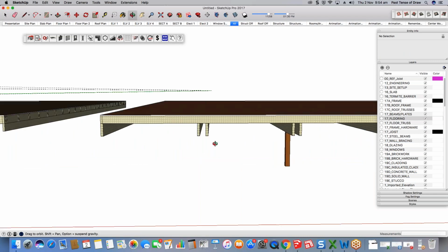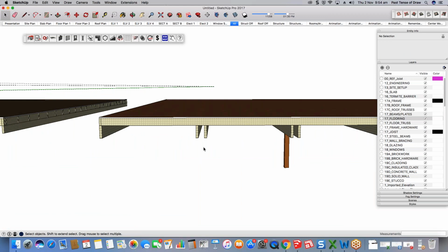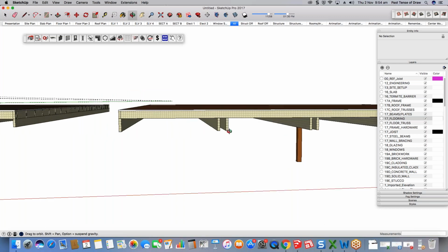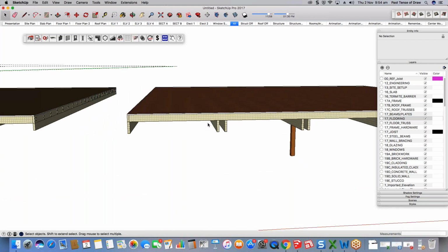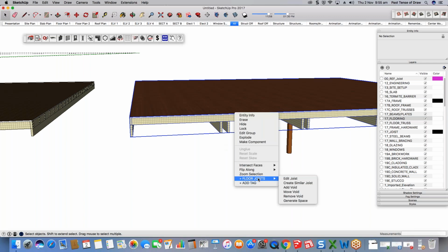It may be better again to go straight into the beam tool and generate those additional pieces of the beams or bearers. It may even be beneficial, like I said earlier, not even to generate the bearer or girder through the joist tool and treat those as a separate item, because it's pretty quick. Right-click, floor joist, edit joist, get rid of the bearers, go into your beam tool, quickly draw one, copy, paste it, move it around, done.